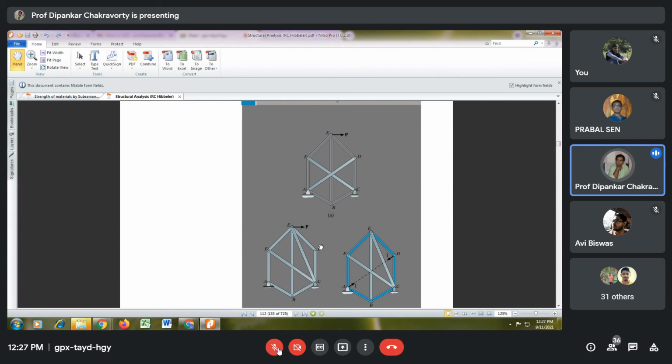Sir, we have to do a cross section because even at joint A there are 3 members. Try to pass a section which will cut 3 members. Sir, cut AF, AD and AB with a section. But that will not help, because all three are passing through the same point, so it becomes method of joints. Three members pass through the same joint. So we cannot do it.